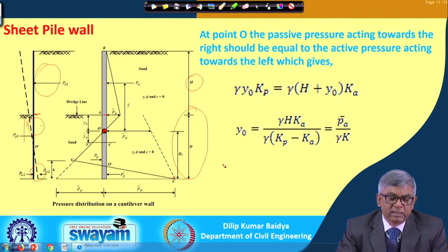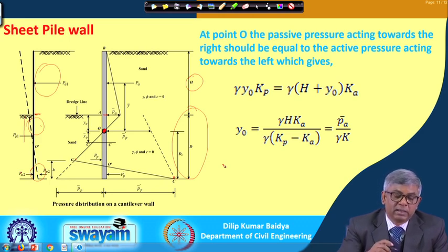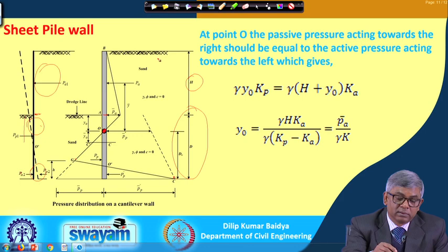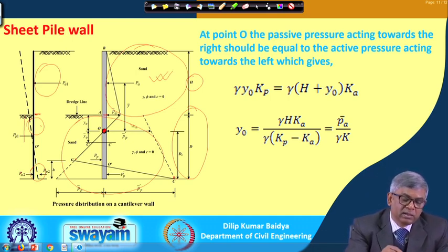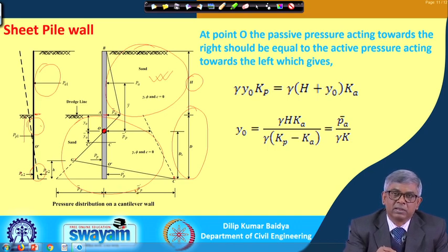So, we can see here again the cantilever sheet pile wall. In the soil, this is the embedded zone and this is the retaining zone. So, two zones are there. This zone generally has to be cohesionless, sandy soil, and for this portion, if it is sand that is good, otherwise it can also be either sand or clayey soil.